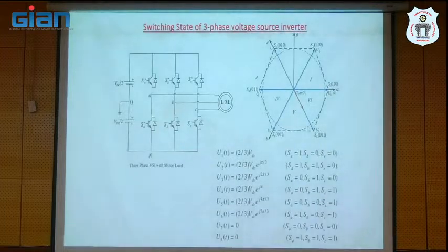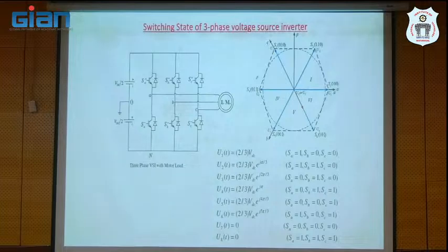Next, one more important thing is, DTC was proposed in the 1980s, while FOC was proposed in the 1970s. The logic behind DTC is, first, based on the operating characteristics of the actual system and the inverter characteristics, by combining these two, the switching states of the inverter and the actual system characteristics, we can improve the performance.